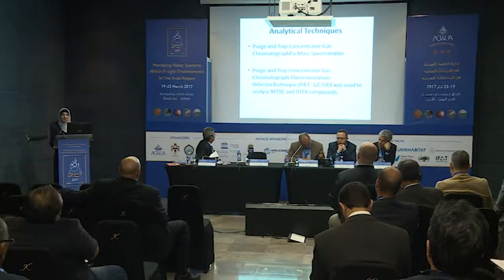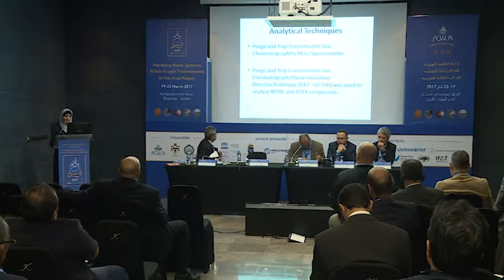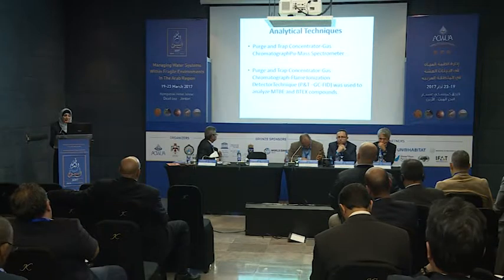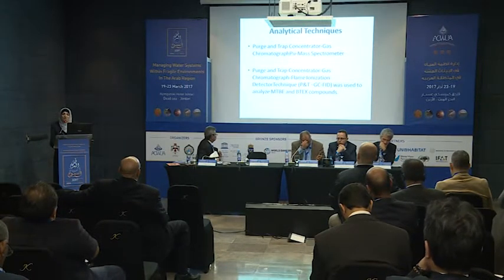The analytical techniques used at the lab to measure MTBE and BTEX compounds were purge and trap concentrator, gas chromatograph, mass spectrometer, in addition to another system, purge and trap concentrator, but now gas chromatograph fitted with a flame ionization detector.